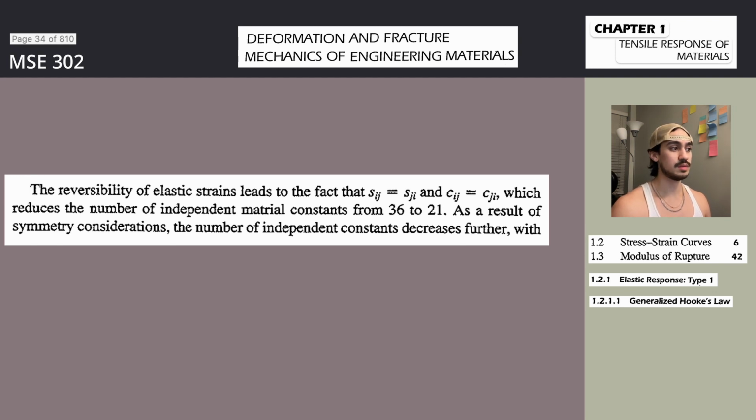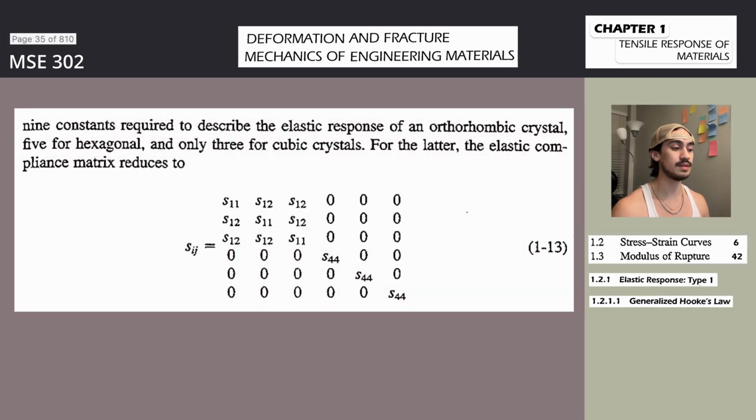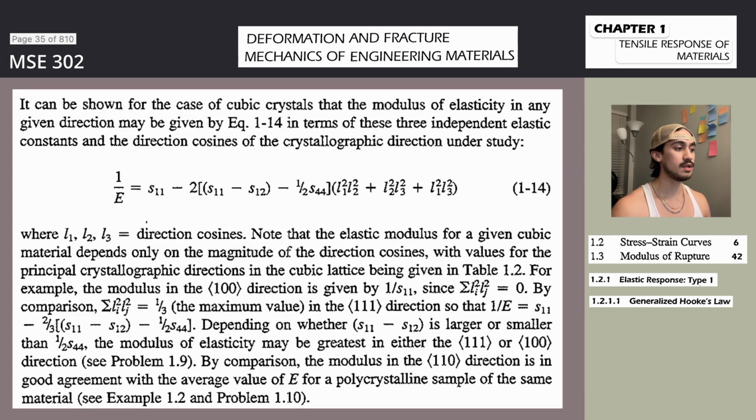However, it is possible for a metal to exhibit nonlinear but elastic behavior. For example, very high-strength filamentary particles, often called whiskers, can exhibit elastic strains in excess of 2%. In this range of very large elastic strains, the modulus of elasticity reveals its weak dependence on strain, something that is completely obscured when strains are very small. For example, note that dF divided by dx in Figure 1.2b decreases with increasing distance of particle separation. As such, Hooke's law, Equation 1-7, represents an empirical relationship, albeit a good one at small strains. Consequently, the elastic limit is approximately equal to the proportional limit and may be slightly higher in some cases.